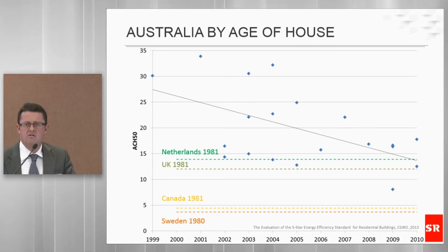Of course, in Canada and Sweden you're also talking about extremely cool climates, and that may again be going too far. In very cool climates, what they tend to do is seal both the inside and the outside layer of the external wall. That would be a significant move away from the way we build today in Australia, and of course it has other effects on weather tightening and how you handle water coming in from the outside of the building.